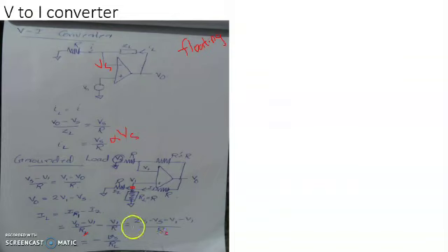So this is VO minus V1 minus V1, that is VO minus 2V1 divided by R. VO is 2V1 minus Vs, so 2V1 minus Vs minus 2V1 by R. V1 minus V1 minus V1 make it 2V1, cancel with this one. So overall this load current IL is equal to minus Vs divided by R.